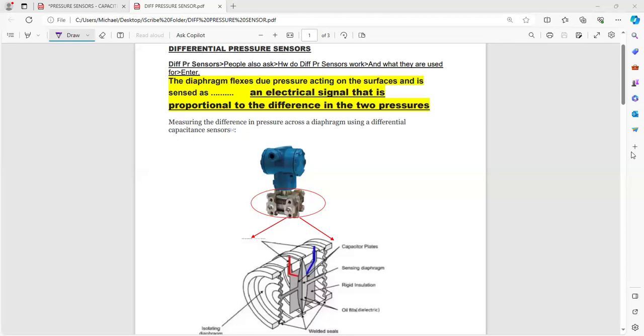Sir, I have one question. Yeah, go ahead. Sir, for the generator lube oil low pressure alarms and trips, is this capacitive type sensor used? No, in your lube oil low pressure, you're going to be having that pressure switch, isn't it? Yes, sir. There is no pressure sensor as such. This is that pressure switch, which is nothing but a box. Usually, I forget the name, Danfoss or whatever it might be.